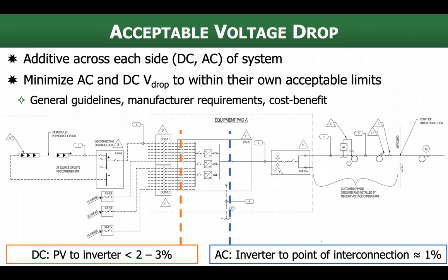Sometimes there might be a little more voltage drop, other times not. It depends on what the system's putting out. Is it worth it? On a large system, doing that analysis really makes sense. Smaller systems, a lot of times, well, okay, we'll just throw a bigger size wire at it. It's not that much. It's going to be fine. It's going to make it work better.